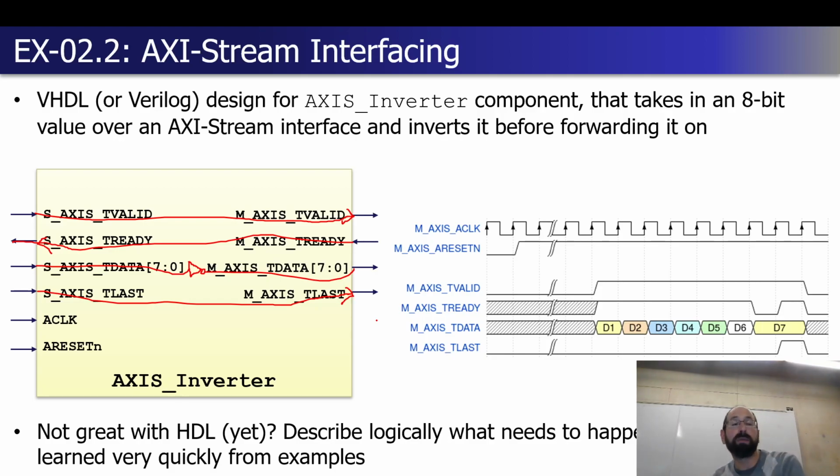Somebody has to tell frame buffer or render output that. It has no way of inherently knowing that this was the last pixel in a frame. There's no guarantee you send it every single pixel anyway. It's getting whatever data it's getting. Somebody, the driver in this case, has to tell it, by the way, you should be done now. You tell me when you're done processing stuff, that means we're at the end of the frame.